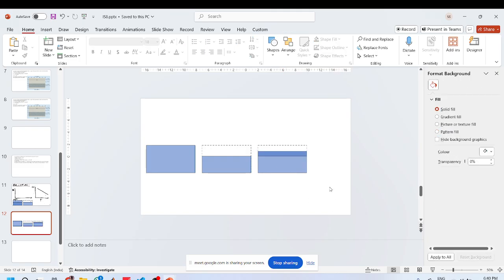Okay. So initially the soil was like this. I loaded it with 100 kPa and it showed some settlement. Then I removed the load and now this is the final shape of the soil. Now if I load this again with 50 kPa, it will not show as much settlement.